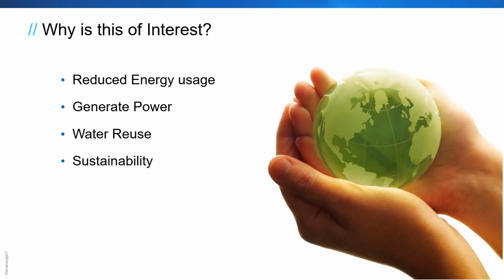So why is it of interest? Why have we been talking about this? Why are people trying to do this? Well, it's to reduce energy usage, right? So anytime you do anaerobic treatment, you're doing it void of air, so you get rid of your blowers, diffusers, all that energy hog that you usually have in a liquid stream, and instead you let the biology do the work for you and generate gas, right?